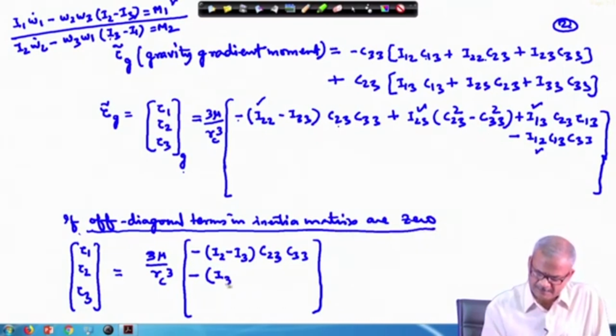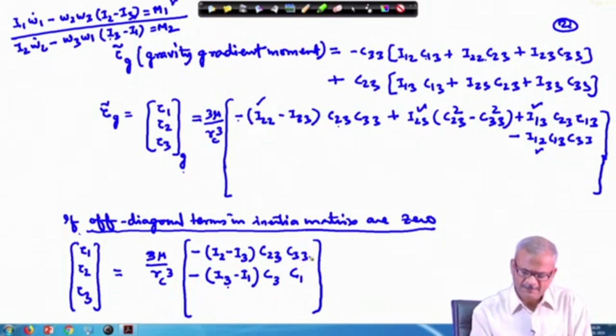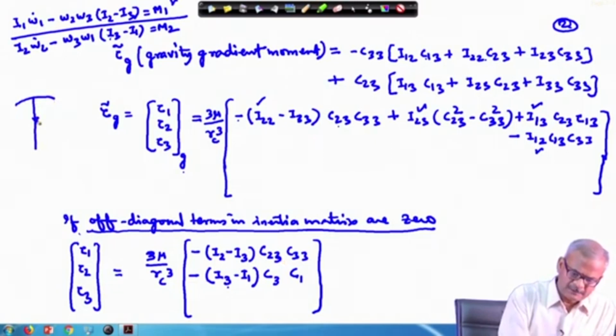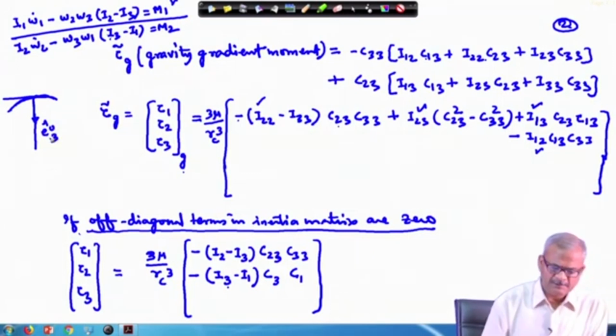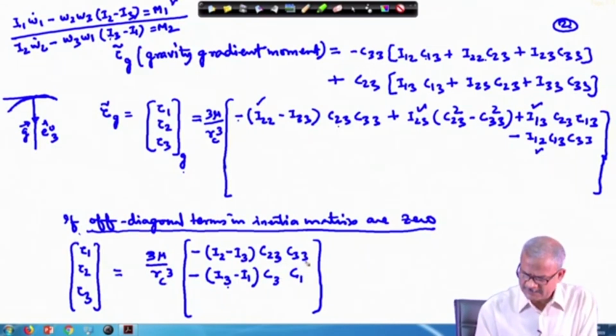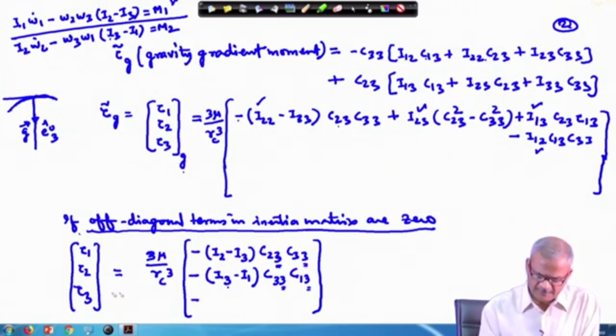So, here from this place we see that this is I3 minus I1, and similarly, you just write C, C, this is 3, so write here 3, this is 1, write here 1. And this 3 belongs to, while we have worked, if you remember that your gravity is acting along this direction, the third axis of the orbital reference frame, that is EO3. So, in this direction your gravity vector is acting. Therefore, in all of them the second subscript will be 3. You see here this is 3, here also this is 3, also here 3, also here 3. The same way tau 3 will be.